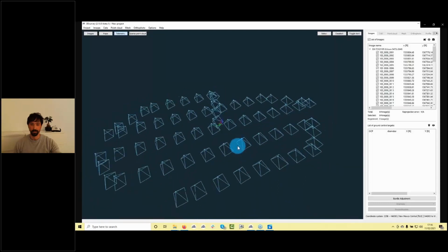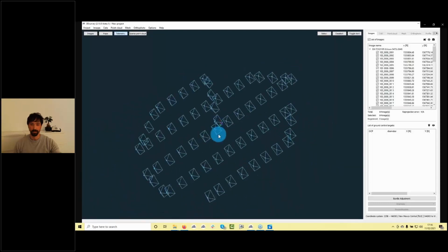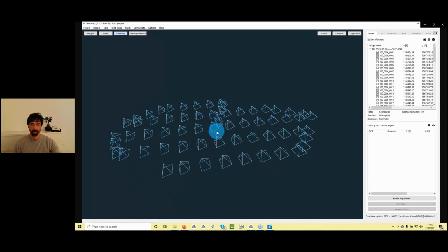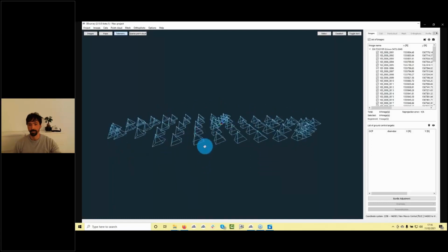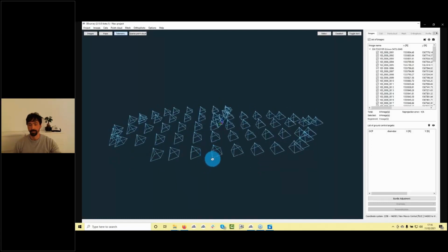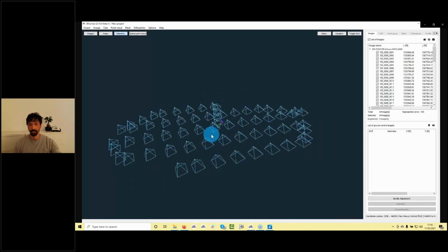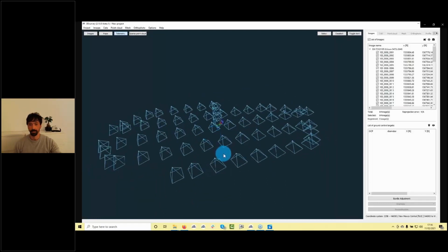In most cases, users trigger the camera perpendicularly down, so 90 degrees down, and in these cases you are the most effective and you get good results. If you are turning the camera forward, you're usually doing a double grid mission to get an even nicer 3D model, but for the kind of project we have here, if the camera is fully down, it's already okay, and it's the fastest way.